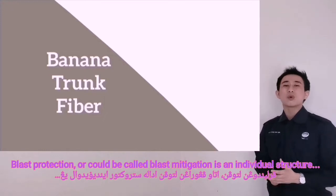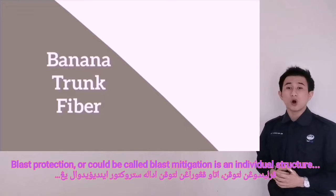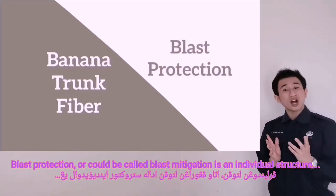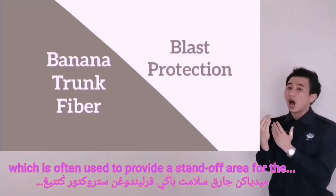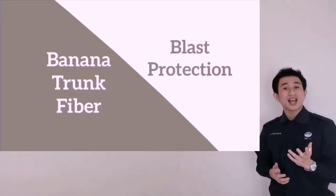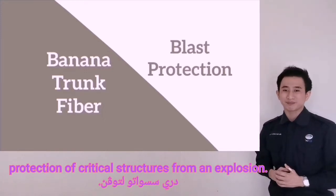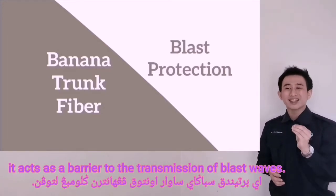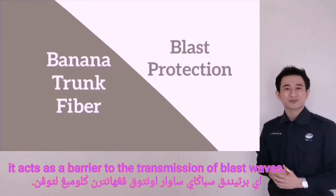Last but not least, we have blast protection, or in our case, also called blast mitigation. An individual structure is often used to provide a standoff area for the protection of critical structures from an explosion. By wave reflection and interaction with the safety wall, it acts as a barrier to the transmission of blast waves.